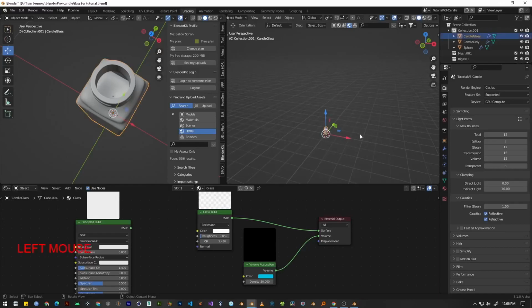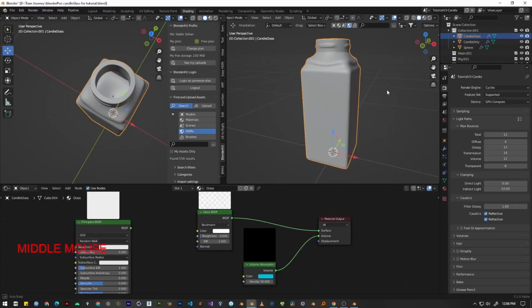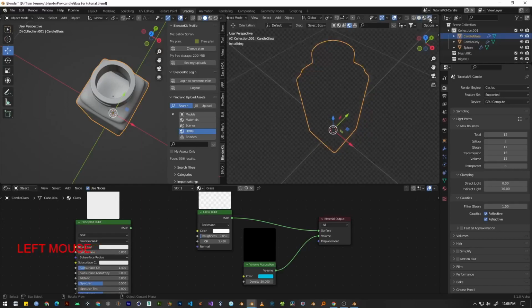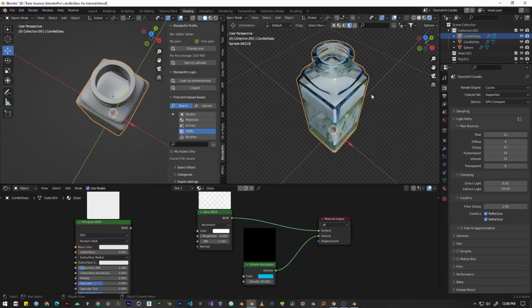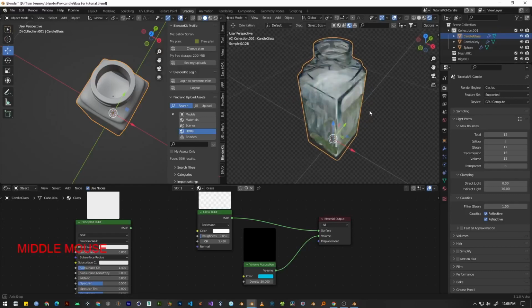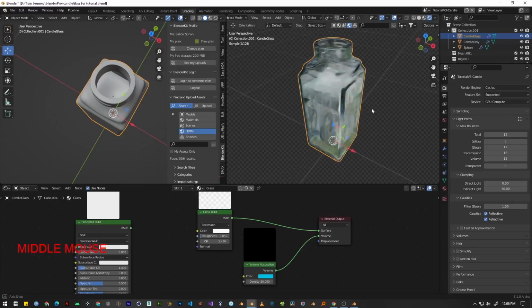Select one object and press the dot key on the keyboard. This will focus the object so that you don't have to manually zoom to the object. This is a very handy shortcut. Now we will fix the glitching candle. This type of glitch happens when two surfaces stay in the exact same position. So fixing this type of problem is very easy.